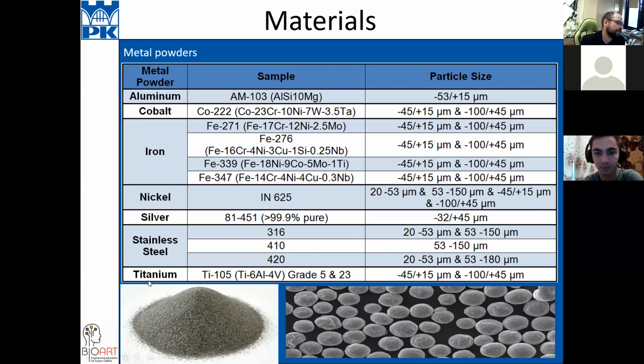Of course, you can also use titanium powder, but also the particles must be very small, and you must remember that when you use this kind of powder, stainless steel or titanium, they hate oxygen. No, sorry, they love oxygen. That's why we must protect it. That's why we use a closed chamber, and we use a lot of protective gases, and very pure protective gases. Pure protective gases, expensive protective gases. This is simple math.